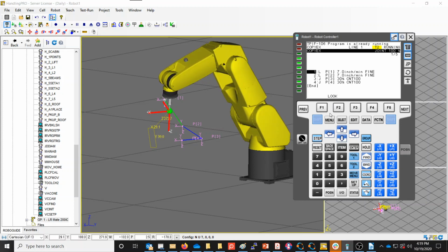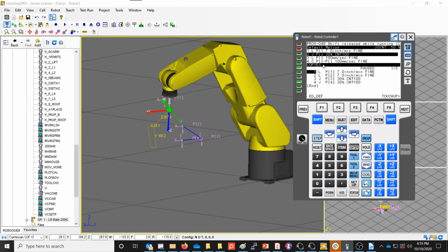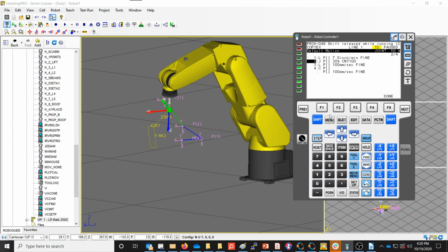All right, but again, to edit this, I pressed F1 without pressing Shift, and then I could select one of the 4 instructions. And out of those 4 instructions, if I didn't like any of them, I can hit Edit Definitions, and then I can come in here and edit one or all of those predefined settings and add my own that I prefer and paste in there. So that's where those come from when you start doing shift point into your program. It's coming from one of those 4 defaults, which is using the one that you last selected.